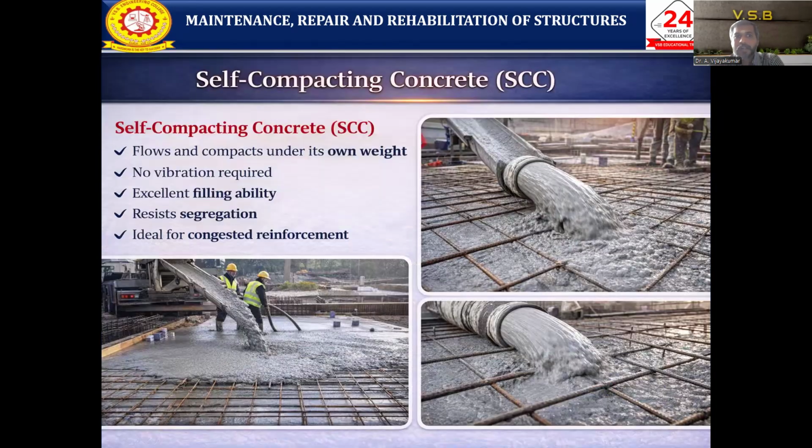Next one, self-compacting concrete. The name itself says it is self-compacting. When you start pouring the concrete, due to gravity it starts to flow under its own weight. Okay, so no vibration is required. Automatically it will flow, with excellent filling ability. It will go into all the places and fill them.